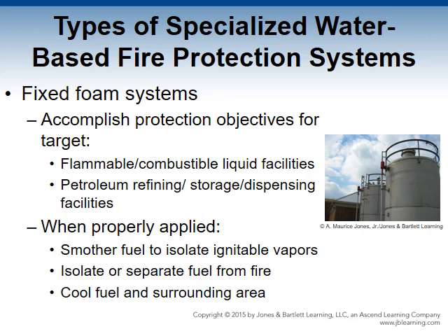The goal of designing and installing these systems is to ensure the system will accomplish one or more of the protective objectives, either extinguishing, preventing, controlling, or providing exposure protection for the following: flammable and combustible liquid processing, distribution, and storage facilities, large quantities of ordinary combustible material, or petroleum refinery storage and dispensing facilities, like tank farms, chemical plants, aircraft hangars, power plants, and rolled paper storage facilities.